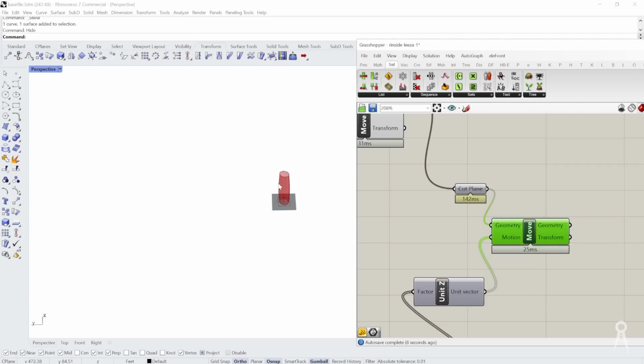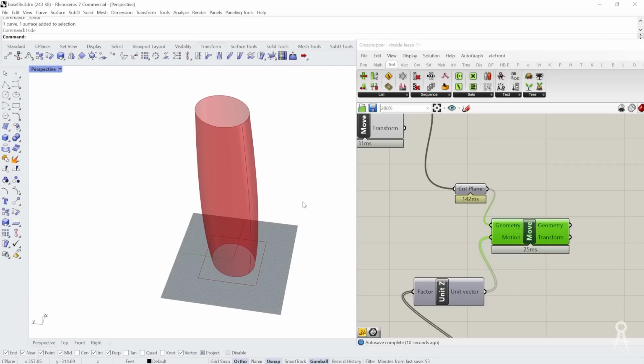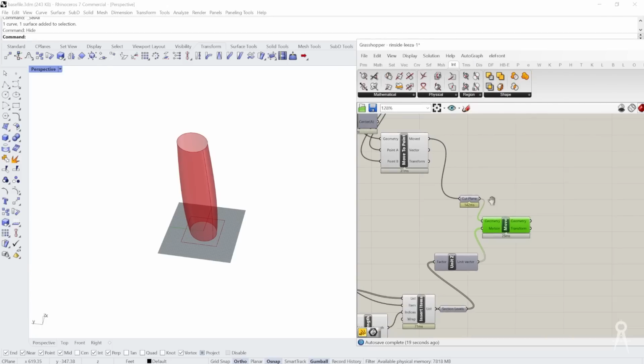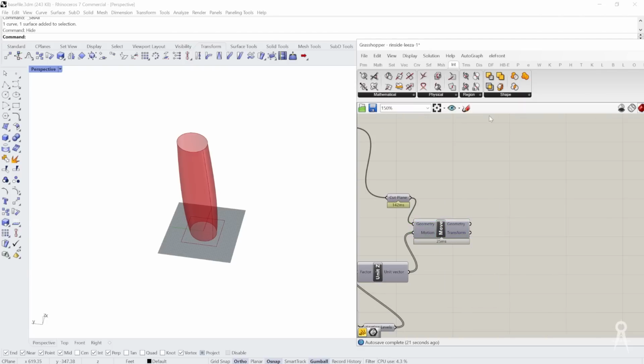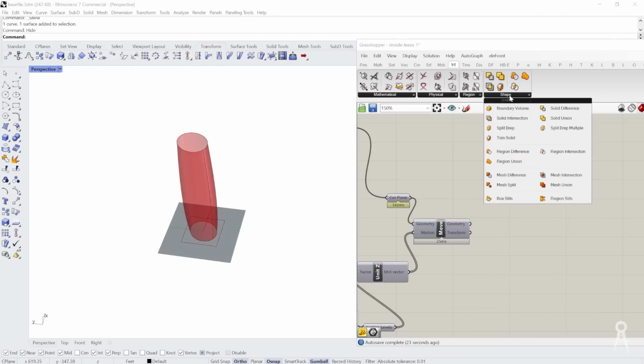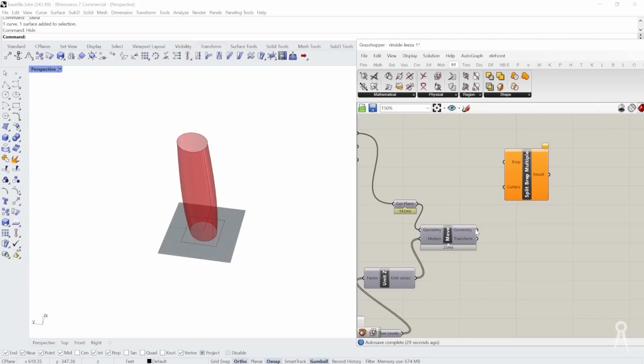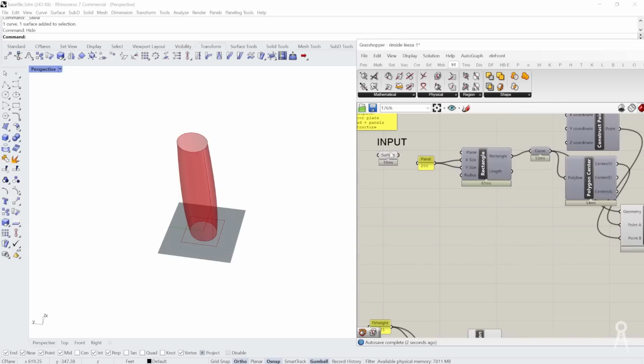The thing we want to do is cut this form using that, and that's going to be using our transform, intersect function. We'll just be using our one B-rep and cutters. So you just see split B-rep with a bunch of other items. Just get your cutters here. These are all of our cutters, and our main surface is here.